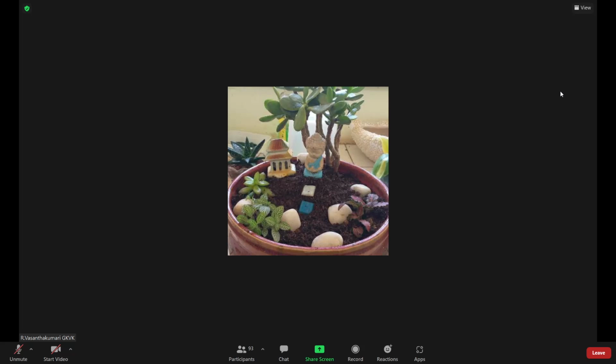At the skirt there is a hole, which I have not drawn here. That hole is meant for the piston pin. And you see that there are two types of rings. One is the compression ring, and the other is the oil ring. The compression rings are placed above, near the top of the crown, whereas the oil rings are placed at the bottom